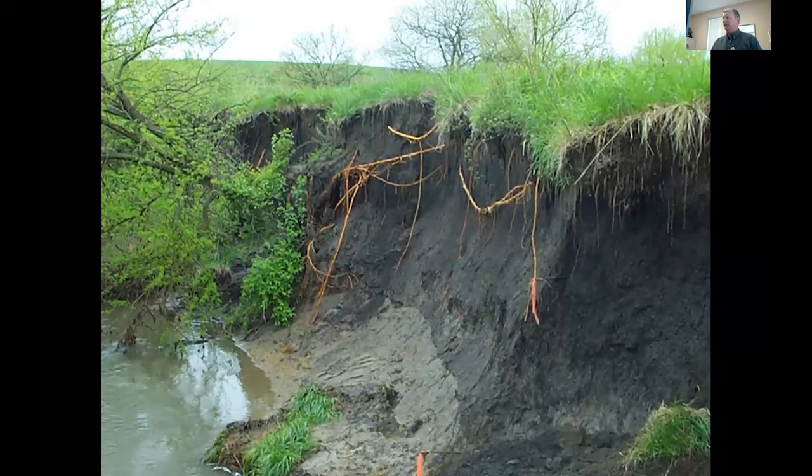After the bed, once again, you get into stage 3 and 4 channels, and the channel's starting to widen. You get things like this happening where vegetation alone is not able to stop channel migration patterns. It's trying to reestablish some meander pattern, and it's undercutting vegetation that's on the bank. That vegetation, especially tree roots that tend to hold the soil in place, winds up falling into the channel. Then it continues on its path.